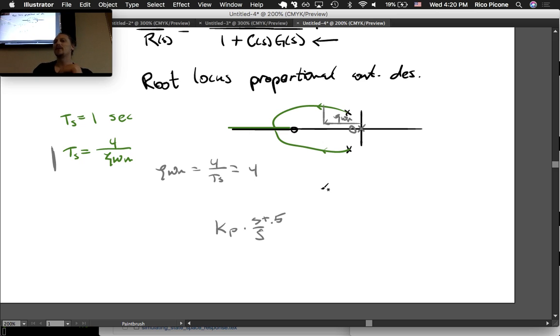So it's going to put a closed loop pole in here, but if you look at the locus, it's in here. There's locus in between this pole and the 0. And notice that this means that it's going to be a very close to your real axis pole. Kind of going to mess up your transient response potentially. So it could slow things down, could cause problems. So we might need to move this 0 leftward some, and we could play with where that 0 location is.